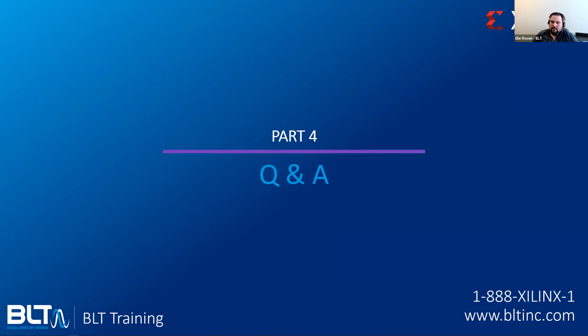Oh, that's a great question. So the AI engines, as part of the intelligent engines of the Versal architecture, would connect to the DDR by instantiating an AI engine core inside of the NoC. And so by selecting that the part that it's connecting to is an AIE, an AI engine, is how you would enable the AI engines to talk over the NoC.